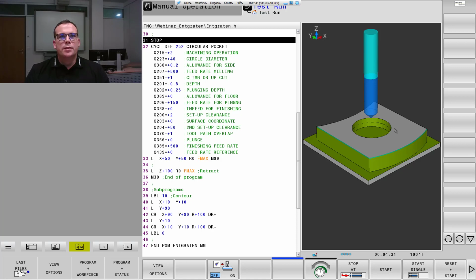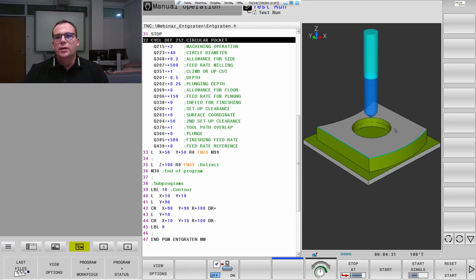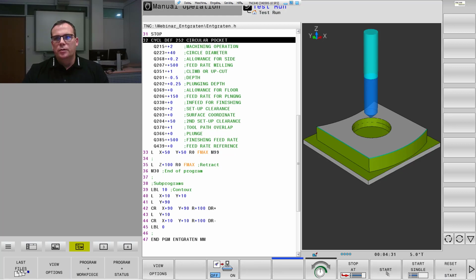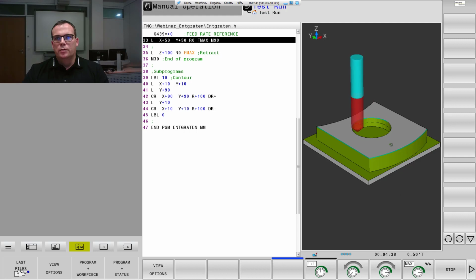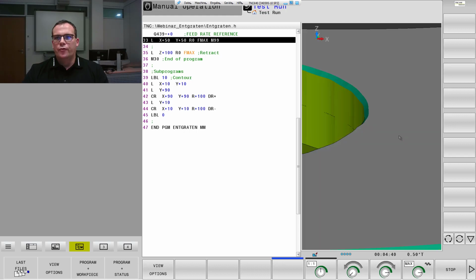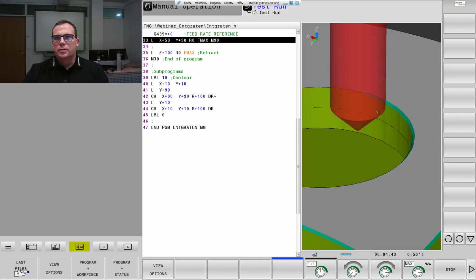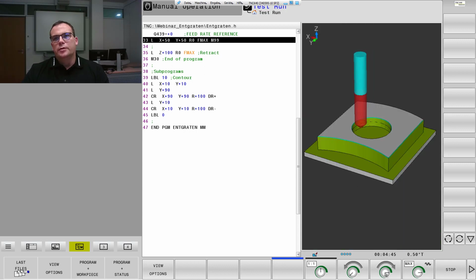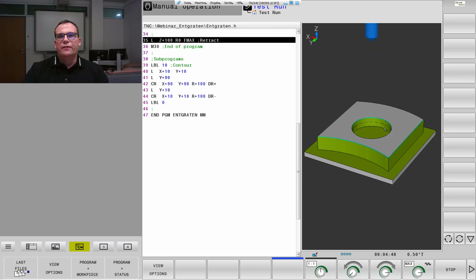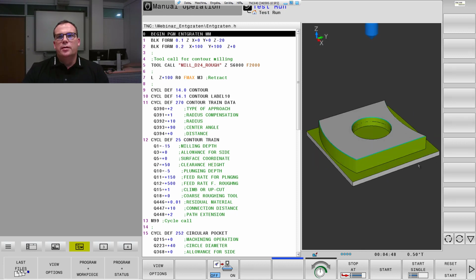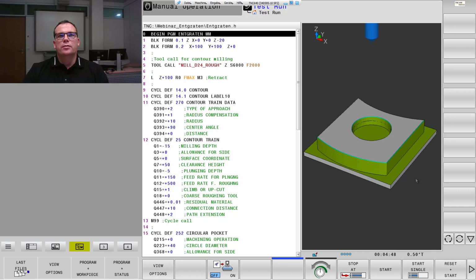Then we can say go to 32 and here you see the same chamfering also for the circular pocket, and that's an easy way to program a chamfer directly on the control with our milling cycles and everything. And if you define it like this, you can also see the result in the simulation, and then we can also check if the size is okay or not.